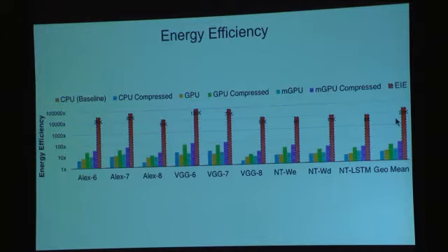So I get another reduction in energy by not doing the 32-bit floating point. And then I get this 120x advantage by being able to fetch my parameters from on-chip SRAM at 5 picojoules per word, rather than from off-chip DRAM at 640 picojoules per word. And if you multiply them all together, it actually comes up to higher than 24,000.